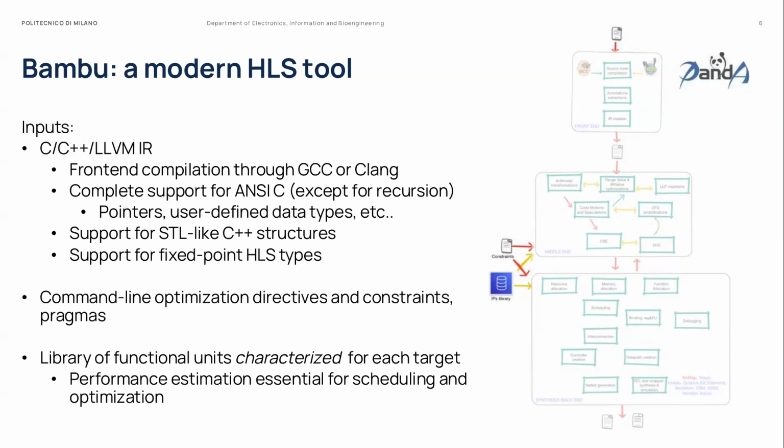This is done through front-end compilers that are standard GCC or Clang versions. We support many of them. We have almost complete support for anything you can write in C or C++, except for things that don't make sense on hardware, like you cannot have recursion with unbounded depth, because once you fix the hardware, there it is, you cannot add more hardware resources at runtime. For the same reason, you cannot dynamically allocate more memory in your application. That doesn't make sense in hardware. But apart from this, basically, you can write anything in it.